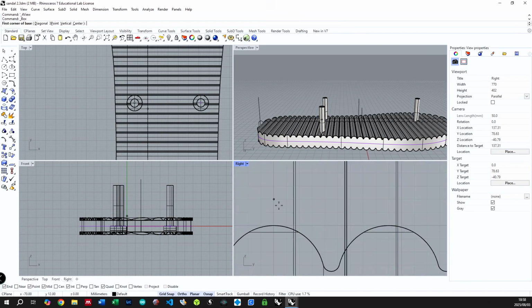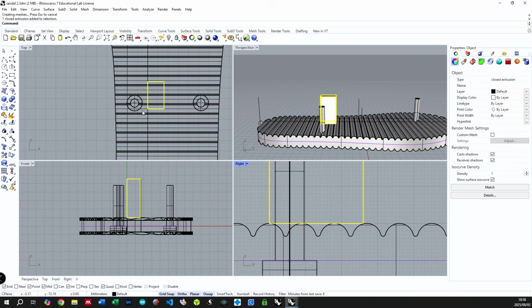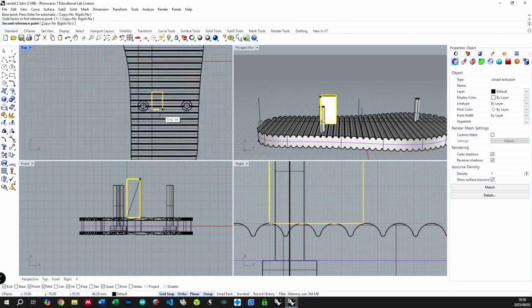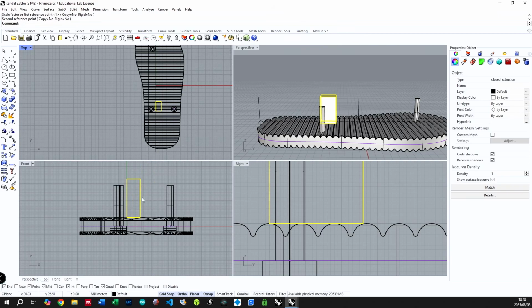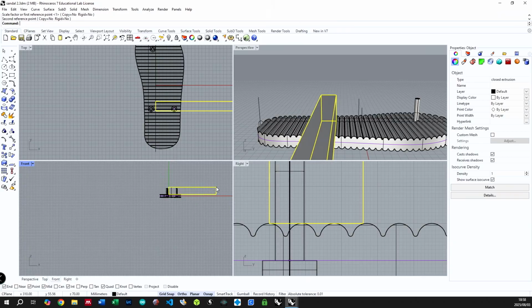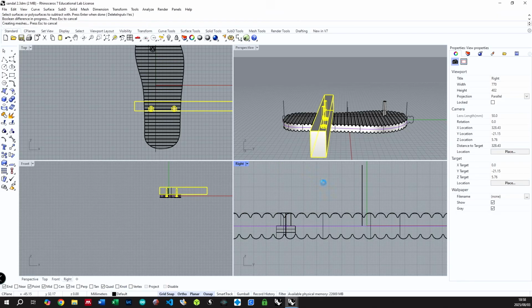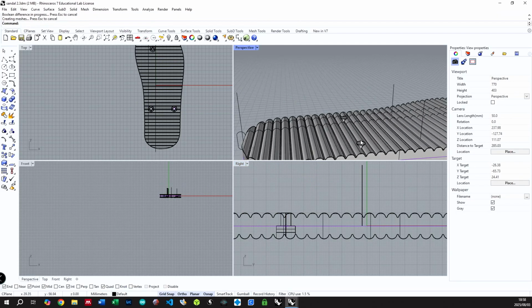I'm just drawing a block that's level with my sole, like that. And I drew that badly. I'm just going to scale to make it bigger from there to there, making it, ooh, I'm doing that very badly. Just making that wider. There we go. I can use that to cut off both of those rear lugs. So I'm going to go ahead and say I want a Boolean difference, keep those two lugs, and cut off with that guy. So I've cut those off flush there.